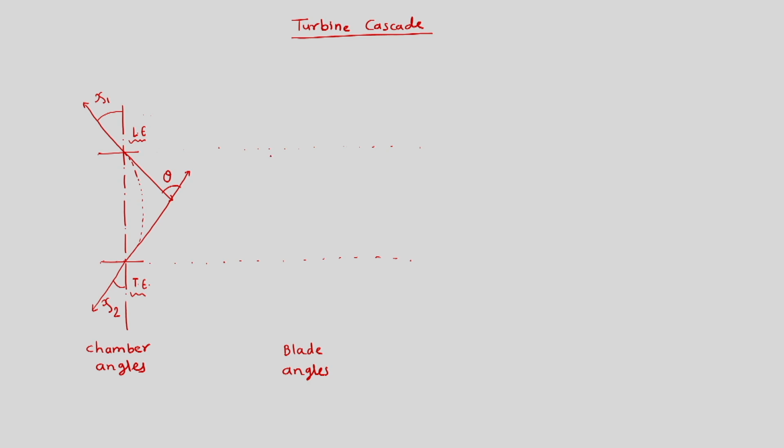Blade angles over there were the angle for the relative velocity. In the cascade tunnel the blades are stationary, so the absolute velocity is going to make a certain angle, but these blade angles over here are defined in a different way. We are just going to draw that. So this is, suppose, again the axis.